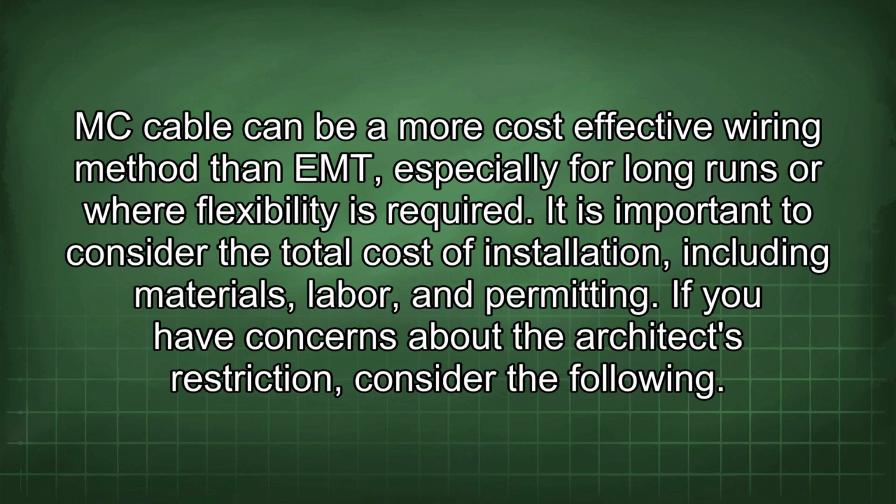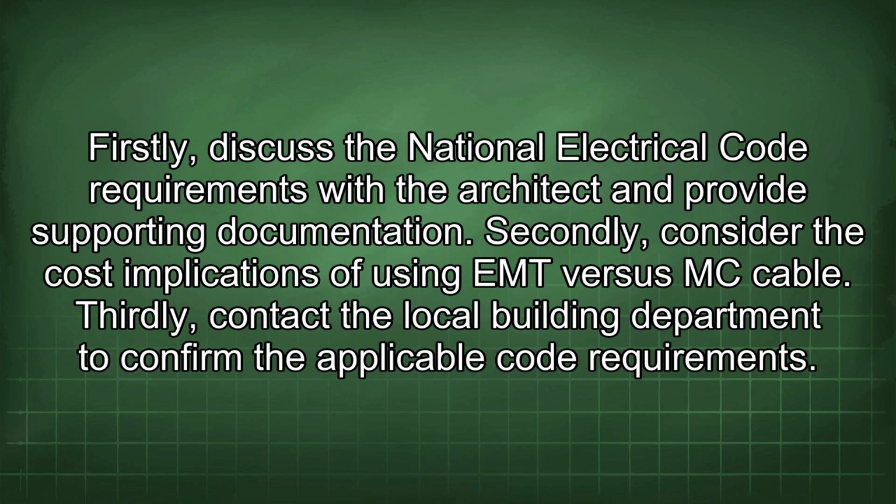If you have concerns about the architect's restriction, consider the following. Firstly, discuss the National Electrical Code requirements with the architect and provide supporting documentation. Secondly, consider the cost implications of using EMT versus MC cable. Thirdly, contact the local building department to confirm the applicable code requirements.